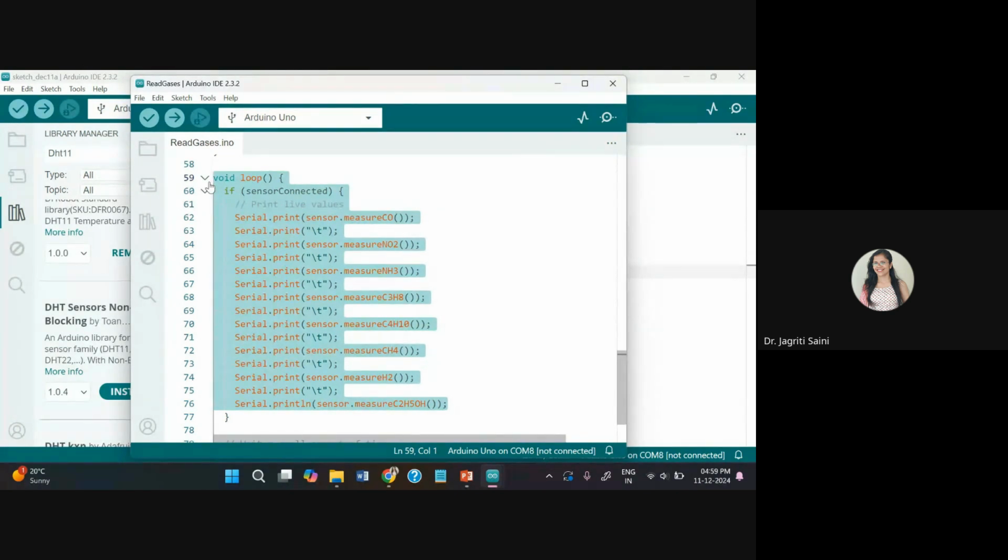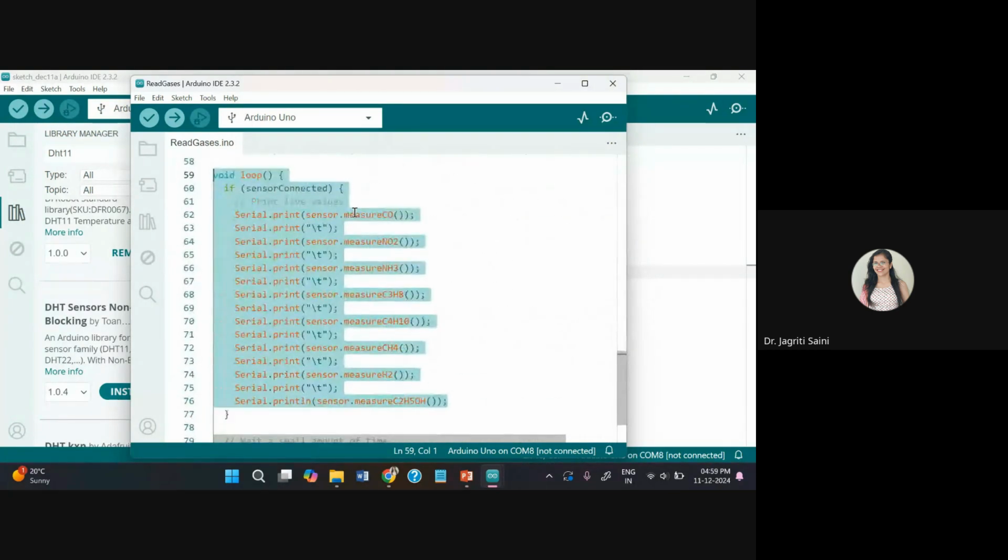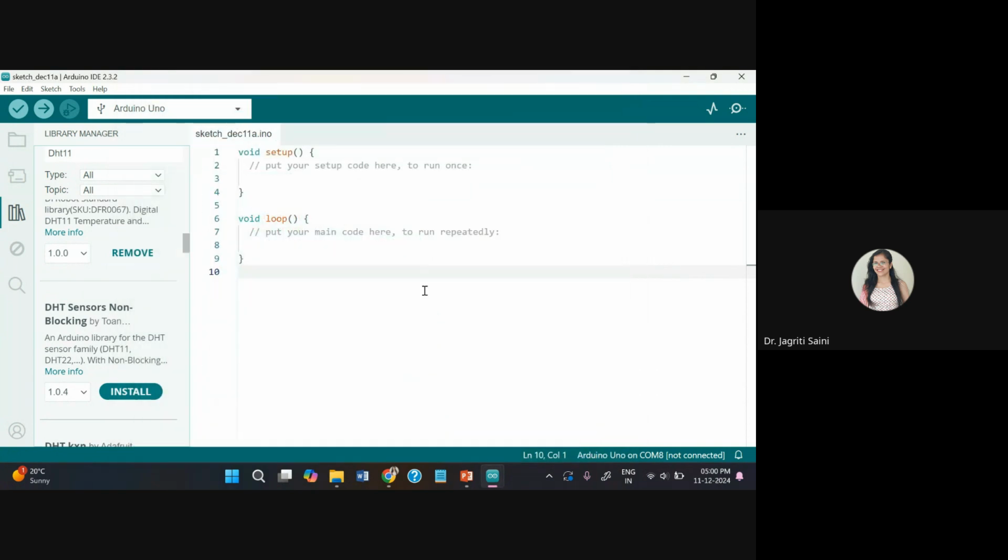So on the analog channel, you can connect it directly with A0 and A1 or A2, A3, any of the pins, and you can read them directly from your code to run it independently on the system. So that is also possible. Either you can use functions from the library, or you can use analog read functions that are available within Arduino IDE by default.